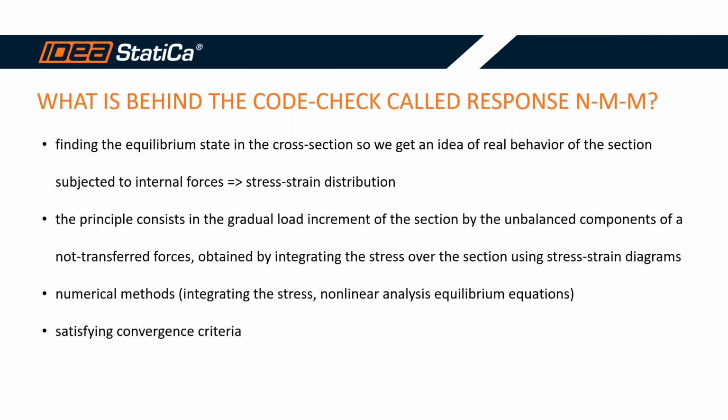In general, there are 3 types of material: concrete, pre-stressing steel, and reinforcement. This method is based on numerical methods, especially when we need to integrate the stresses or solve nonlinear equilibrium equations. The whole method is also based on an iteration process, so we need to satisfy the convergence criteria.